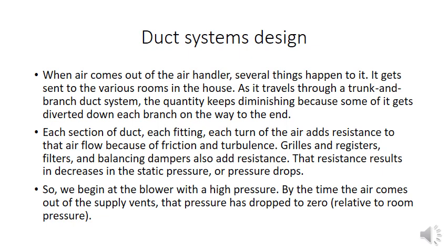Each section of the duct, each fitting, each turn of air adds resistance to the airflow due to friction and turbulence. Similarly, some filters and balancing dampers are also used, and they add resistance to the flow. That resistance results in a decrease in the static pressure, ultimately the pressure drop. So when we place a blower to maintain a pressure, air comes out of the supply vent and the pressure has also dropped. Sometimes it is even zero.